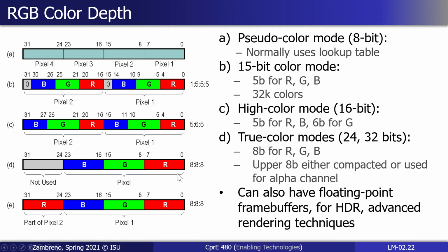For our 8-bit color, this is also a common conundrum. We know that we want 8 bits for R, 8 bits for G, 8 bits for B. It's a very common use case. Do we just keep everything as 24-bit values and then pack things into memory correspondingly? Or do we use that additional 8 bits just as a spacer to make our operations all 32-bit? Or do we try to implement something in those additional 8 bits? So actually, there are three possibilities. That upper 8 bits either doesn't exist and we're just storing 24 bits at a time, or it's just blank, used for nothing at all, or it can be used to store other information such as an alpha channel for transparency information in an individual image.